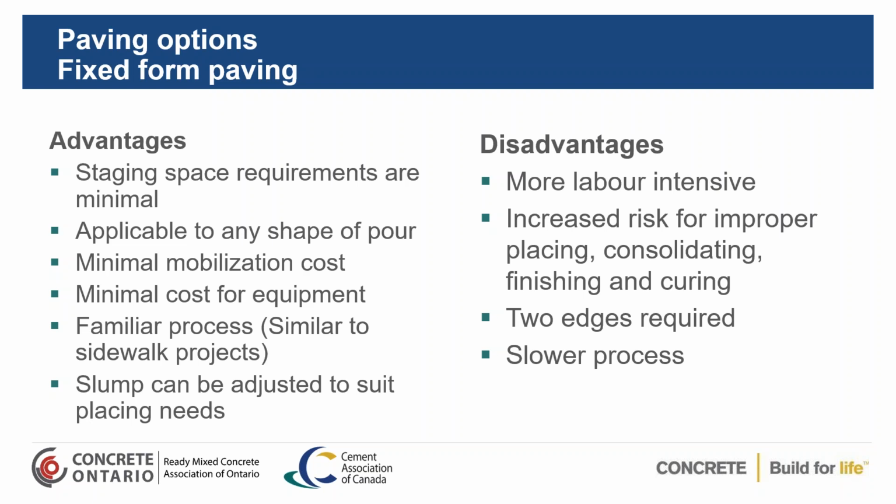Now, some of the disadvantages would be you have a more labor-intensive process. You have an increased risk for improper placing, consolidation, finishing, and curing, because instead of a machine doing that, a lot of the work is being done by hand. So you're relying on the workers to be knowledgeable. That's why we recommend the flat work finishing course that's put on by the Ready Mix Association.